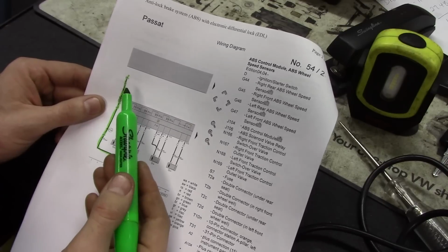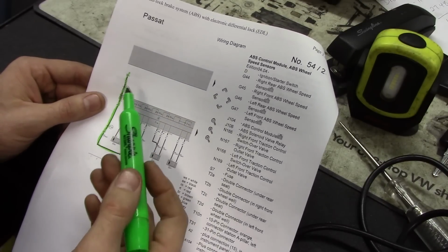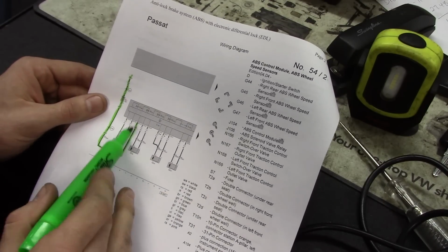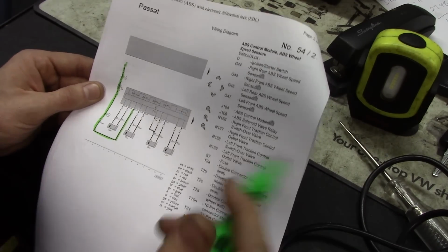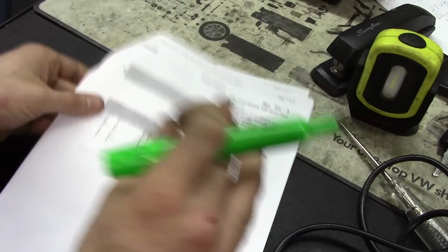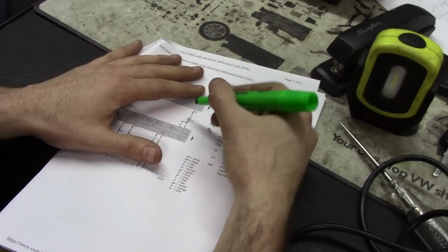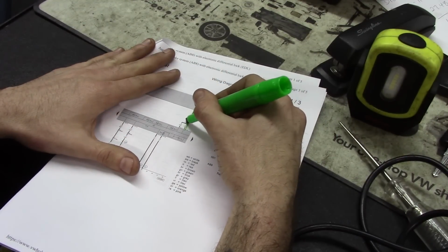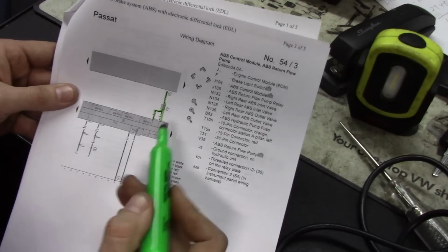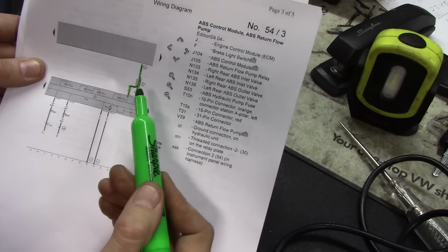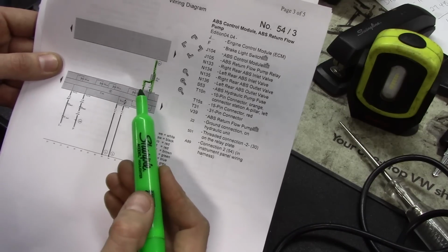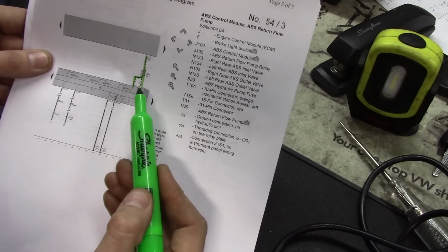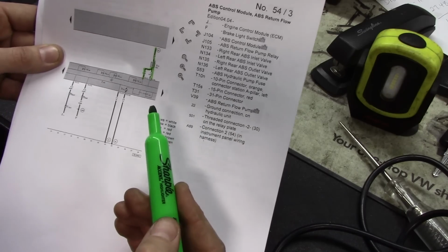It's a 10 amp, and that comes from the ignition switch. That looks like it's pin 15. It's going to be a black with blue wire. Don't see any more on this page. There's another power feed right here. There's actually two of them. S53, it's going to be a 50 amp that supplies power feed on pin 17 and 18.